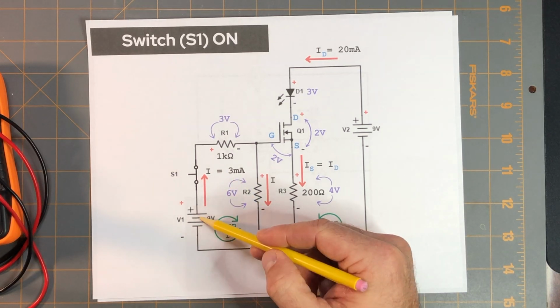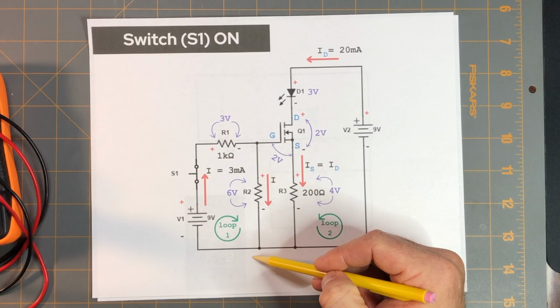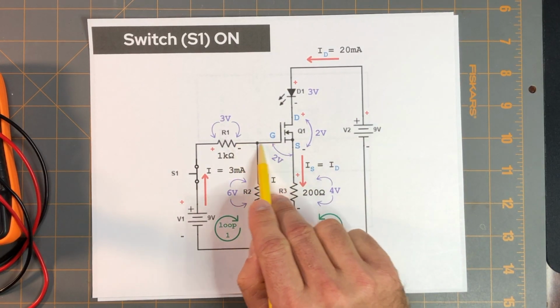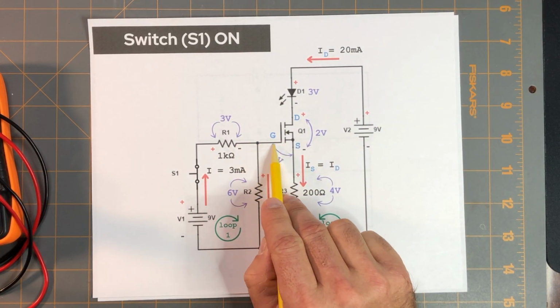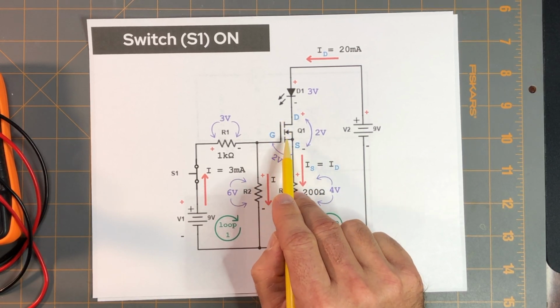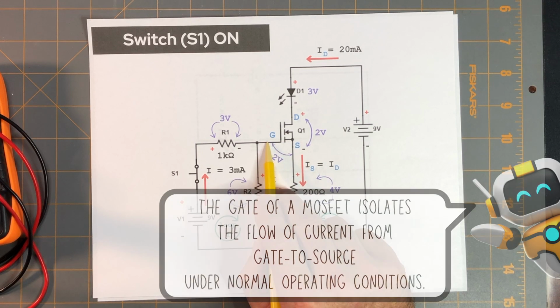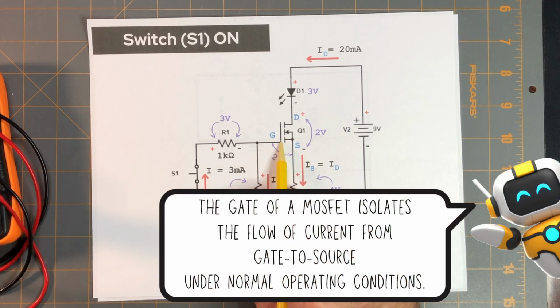And like I said, this loop of the circuit is in series because that current is not going through the gate, because the gate of a MOSFET acts as a capacitor. So we can say ideally that there's no current going through the gate.